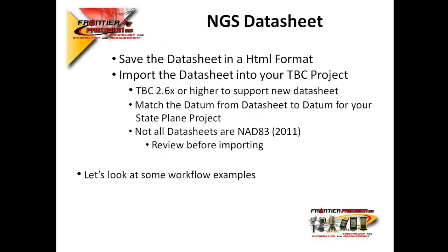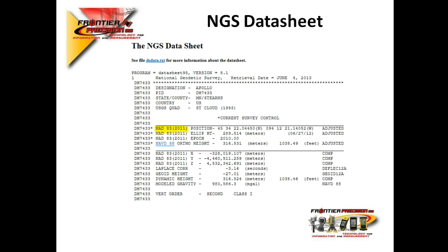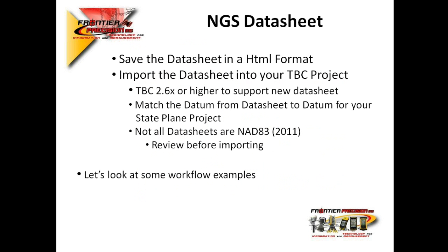with OPUS, we can save that data sheet in an HTML format. We can import that data sheet into TBC, into our project. Note that with the change of this data sheet to version 8.1, that version of data sheet is only supported in Trimble Business Center 2.6 or higher. So TBC 2.6 or higher supports that newer data sheet. Make sure you match your datum from the data sheet to the datum of choice within your state plane project that you're working with. And note that not all data sheets will be reported out in 2011. Make sure you review that.